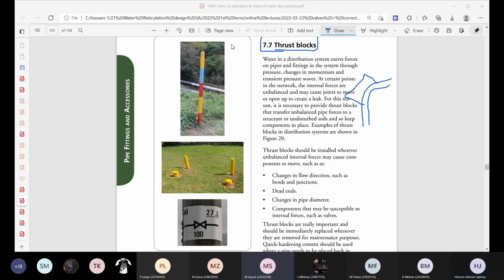With this chapter, must we focus on the valves, water meters and stuff? Not everything. The valves, not even the water meters, I just discussed them. The main thing is the valves, that's our main interest in the network. The context of the water meter would be, for example, in a bulk water supply system, where you can use the meter so you could pick up if there are leaks in the system.